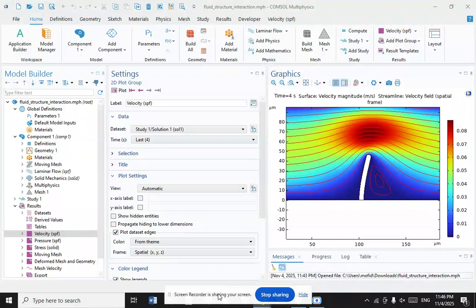The next one is called an iterative process. Because the fluid and structure affect each other, they cannot be analyzed independently. Fluid structure interaction problems require a coupled analysis that iteratively solves the fluid and structural equations until the solution converges for a given time step.